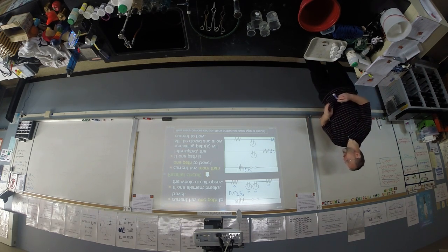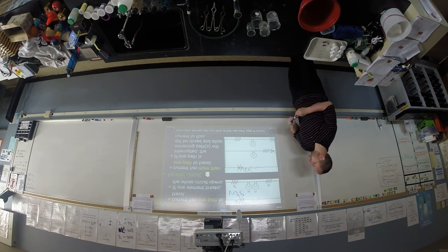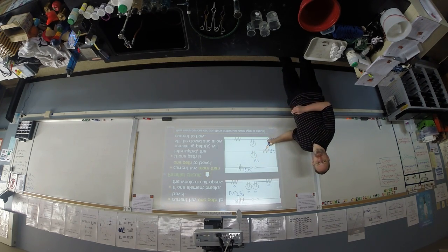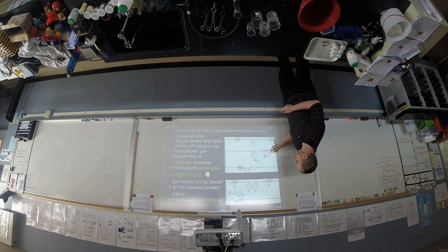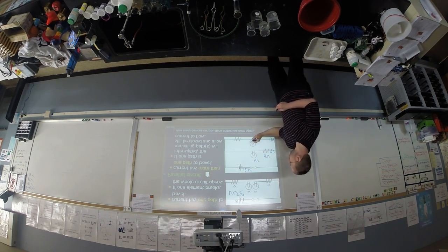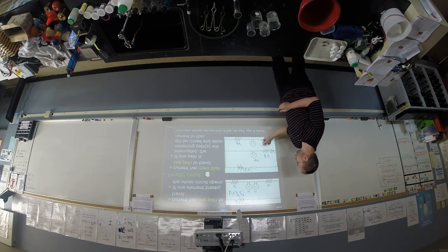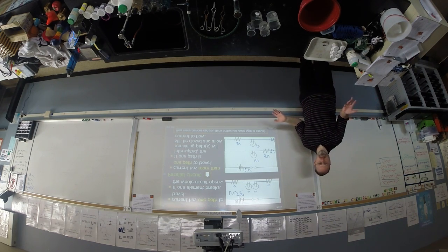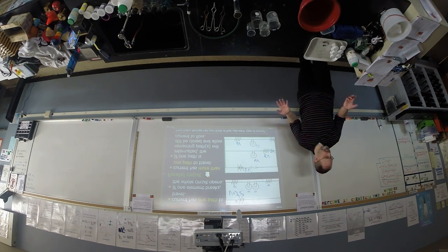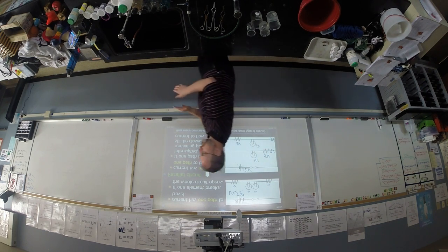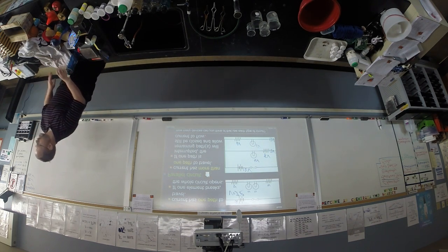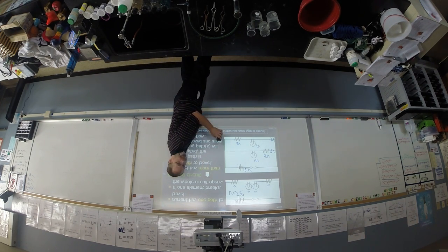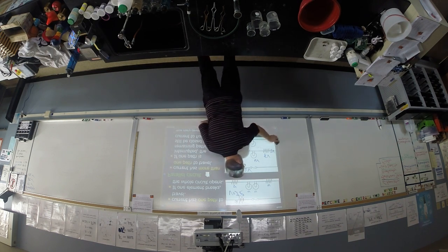Now, if that does make sense, realize in my drawing here, if this light has 4 volts through it, then this resistor must have what? 8 volts. Because this is in series. And if this resistor has 6 volts, then this light must get 6 volts. Are we good? All right. So that's level 1. Level 1 done. Okay. No questions? All right. You will have some eventually. That's all right.